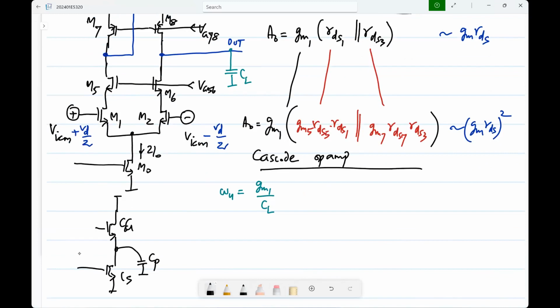So what is the resistance that appears across that capacitor? Yeah, primarily it is the GM of the cascode device. So GM of the cascode device divided by CP is the additional pole. So all these additional poles will be of that order. Okay. So we can consider them to be non-dominant poles, or of course you will design them to be non-dominant poles. They will be at high frequencies. Okay, but nonetheless they will be there. So there will be some effect on the phase margin.